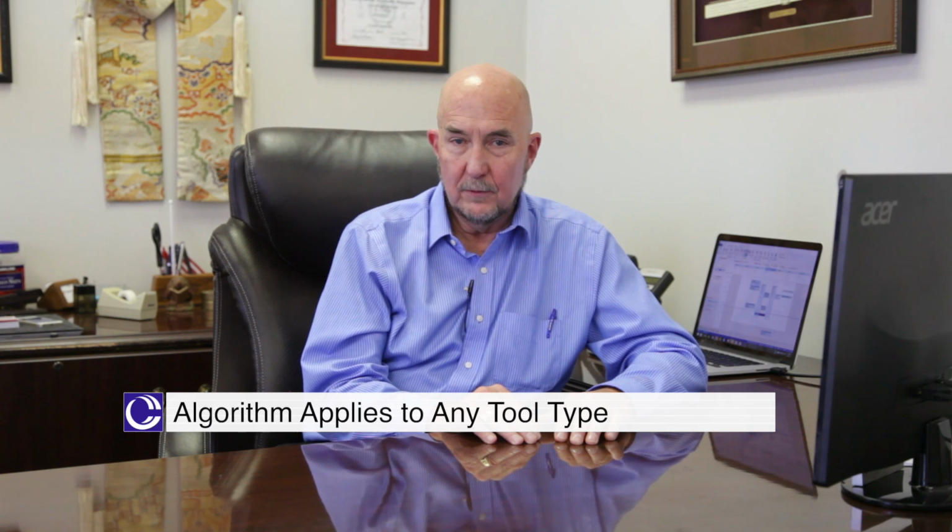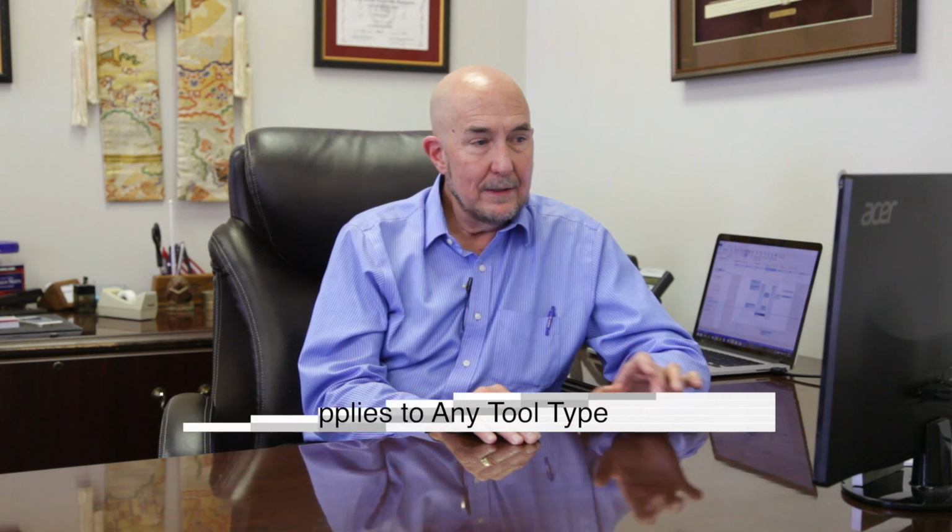And again, the other benefit is that since the E164 parameters that we're referring to are common to all equipment, they are not process specific at all, this algorithm could be developed to apply for any tool type, and then just configured slightly with differences in recipe execution times for those individual tools. So you can see a way that the requirements of the EDA specs for the metadata model in the equipment actually supports a very advanced application that can be done in a way that is optimal for both the tool makers as well as the software engineering staff of the chip makers.